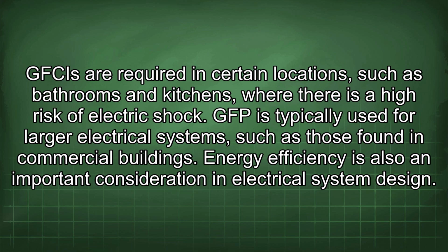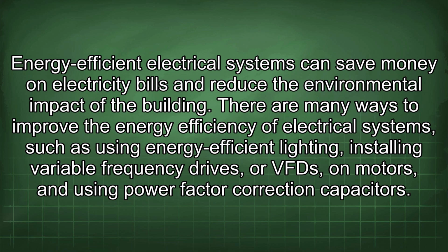Energy efficiency is also an important consideration in electrical system design. Energy-efficient electrical systems can save money on electricity bills and reduce the environmental impact of the building. There are many ways to improve the energy efficiency of electrical systems, such as using energy-efficient lighting, installing variable frequency drives, or VFDs, on motors, and using power factor correction capacitors.